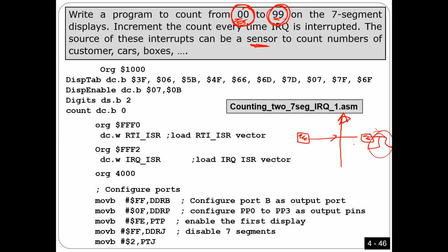The same idea can be used if you want to measure the motor speed, because it's exactly the same idea. We put a disk here. This disk should have two holes. That means we should have two interrupts, or two pulses, every one rotation. So every two interrupts means one rotation. Okay, so how should this program work?